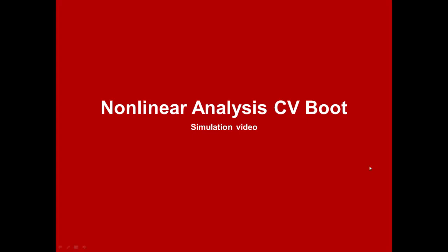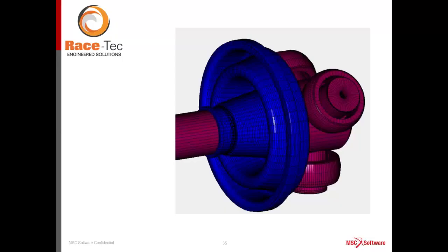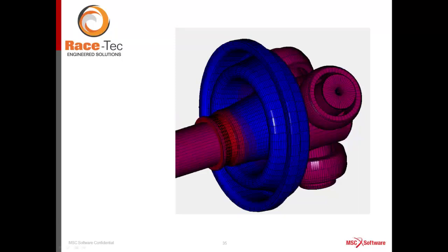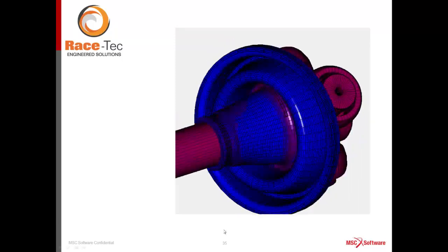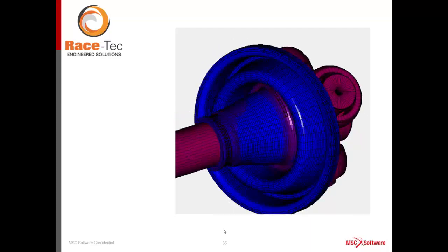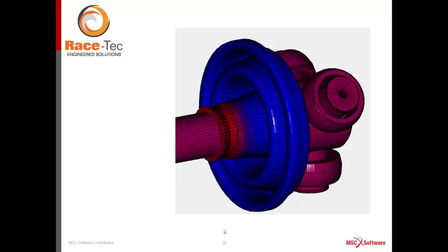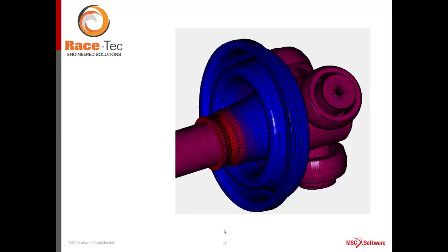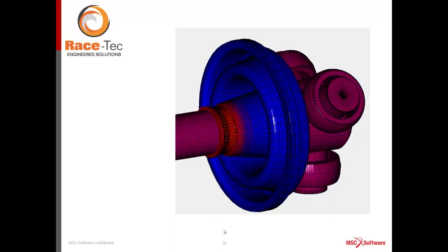Here's a full analysis simulation video of a different type of boot. You can see the boot is expanding to the shaft size, angular deformation, and then finally a steering motion. This is great for us because we can see exactly what the boot's going to do. We can see areas where we have too much material or not enough material, so we can actually refine the design to make it as small as possible.